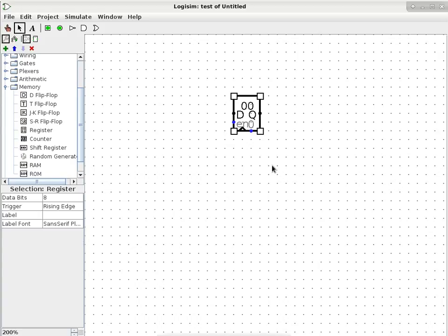There are a few things that really stand out, and we've seen those things for the past hour or so, right? There's D, which is data, the input. There's Q, which is the output. There's EN, the enable pin. The reset pin is labeled 0 because RESET takes up too much space. The only one we haven't really seen is that little triangle. That's the clock. So we have exactly the same pins in the register, except this one is just one single unit.